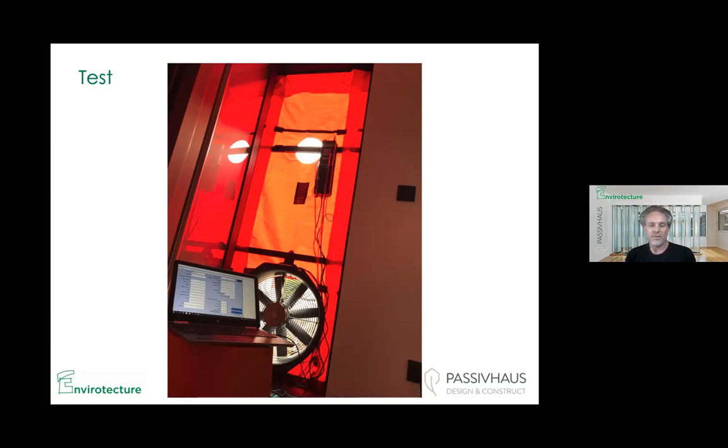The most fun ones are actually the buildings that leak. Passive houses are actually really hard to test because they're so airtight. So they end up with much smaller fans, because that fan in the image there is too big. But also, nothing really happens. Whereas when you test an old leaky building, it's much more fun because you can go around and squirt, what's it called? Talcum powder. Talcum powder is really good because it's nice and light. So you just squirt that near things where you think it leaks. You can normally feel the air whistling anyway. Yeah, really good fun.